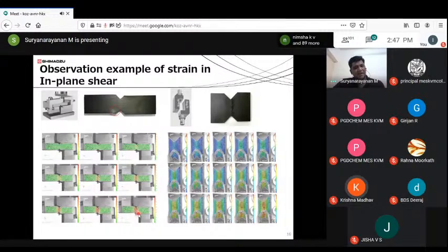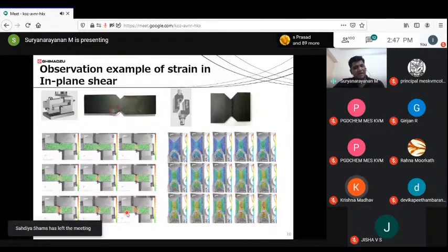This is essentially to understand the strain and stress happening during the actual samples which we produce for our activities and our requirements. We could also see in this sample, since this is a larger sample, we have a great field of view. And as we see here, this is where the stress is analyzed gradually from this point and slowly dispersing to the other parts of the area. And here the specimen has been under high stress.